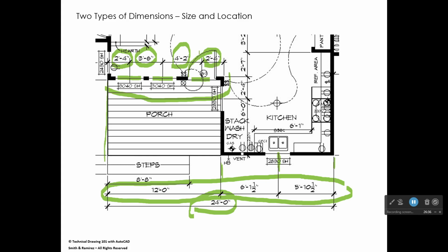And when this door swings open, I want to point something out to you. The hinge would be right there. And we actually call that side of the door the hinge jamb. Okay. And so if you were on the phone with somebody and you're looking at the plan, they might say, are we looking at the hinge jamb on that door? Or are we looking at the strike jamb? This is your strike jamb, right over here on the left-hand side. So the hinge jamb is on the right, the strike is on the left. That's where your door handle and everything would be.